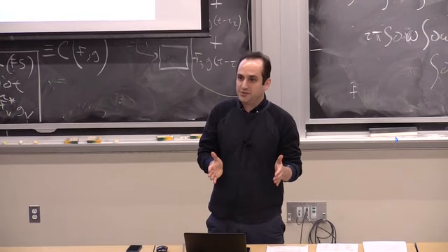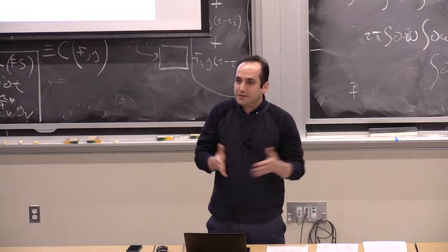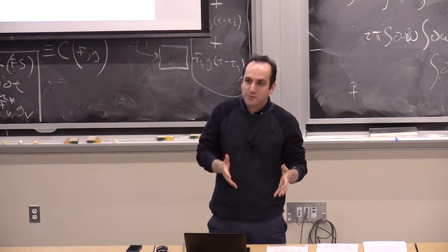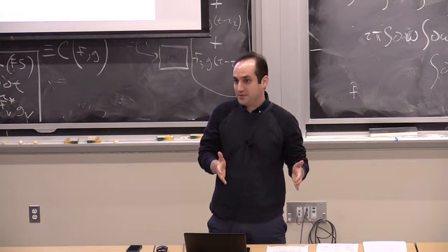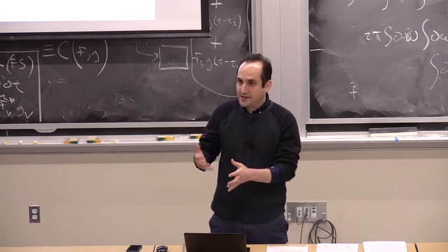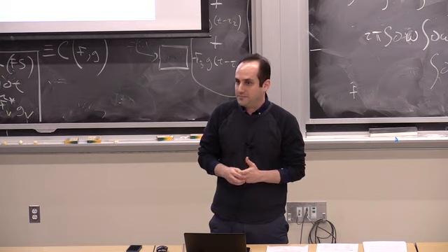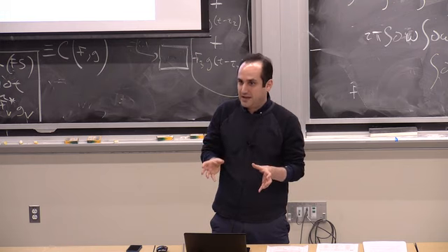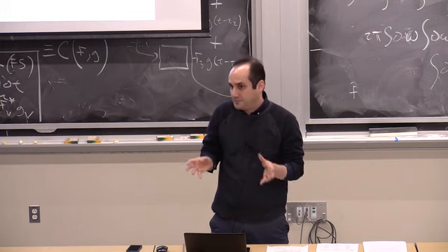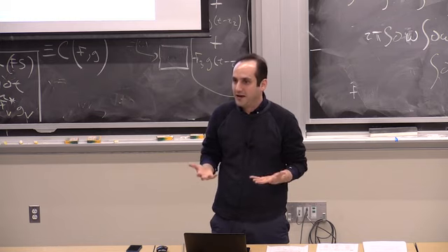Headway consideration is related to maximum waiting time. You don't want really long headways that would force people to wait longer. At the same time, you don't want buses that are overcrowded, with discomfort resulting from the crowding effect. So these are two different sources of disutility in the service that we try to balance somehow.